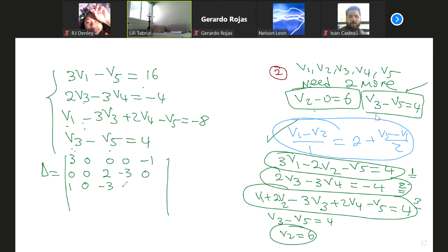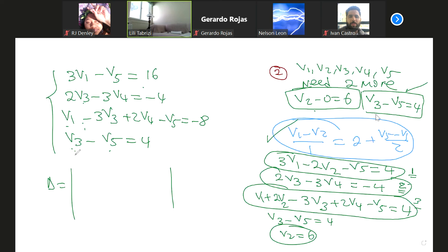Actually, what I'm going to do is, why do I need to use the 0, 0 row? You can eliminate v2. v2 is not the unknown. So you set up your Kramer's rule according to the following: v1, v3, v4, v5. You make it like 4 by 4, not 5 by 5. There is no v2 here. v2 is a constant. So you do it according to this format. So it's 3, equation 1, there is no v2, there is no v4, and minus 1. So you reduce the size because one of them is constant.